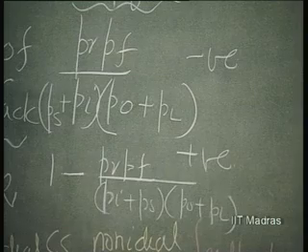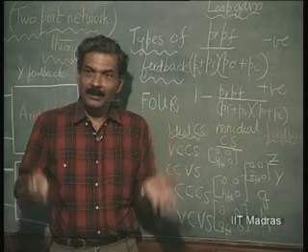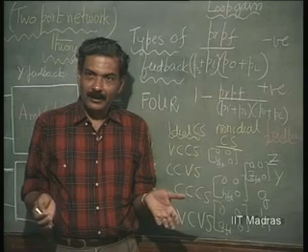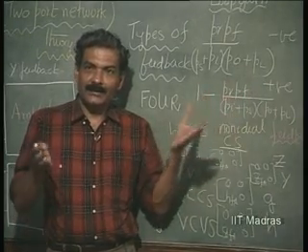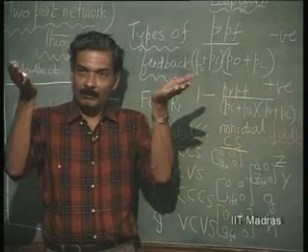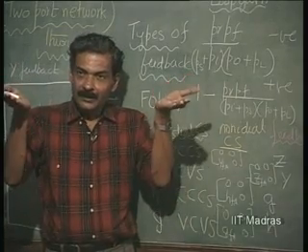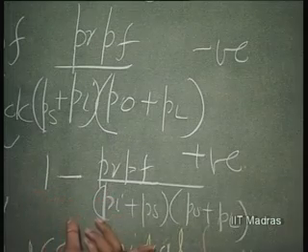If things are in series at the input, the impedance level will increase or admittance will go down by a factor determined by this. If things are in series at the output, again the impedance level will go up. It is going towards current source realization. The factor by which it improves is again the same thing.